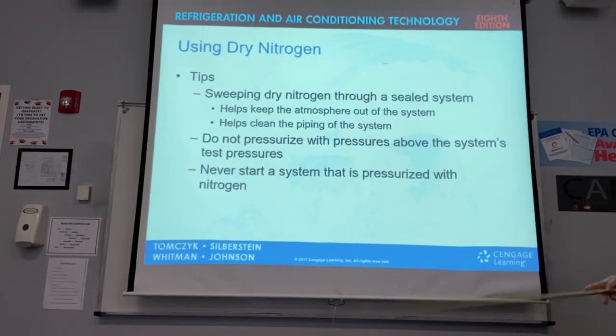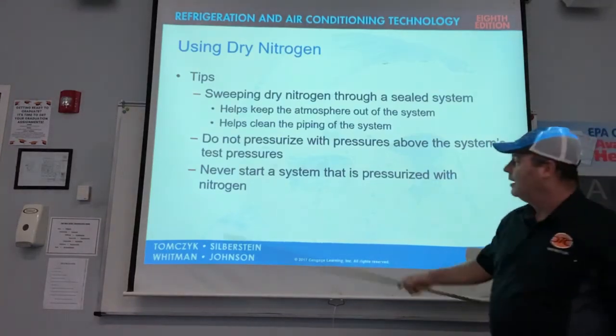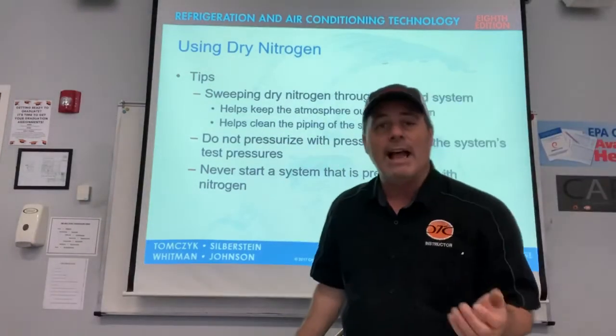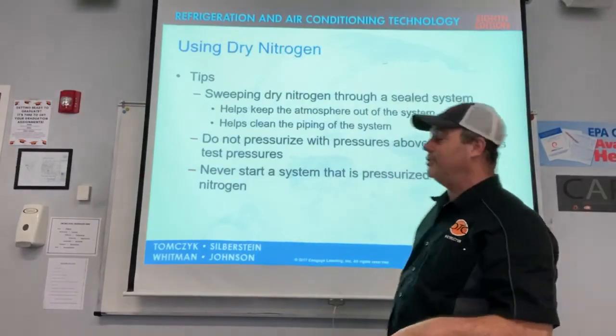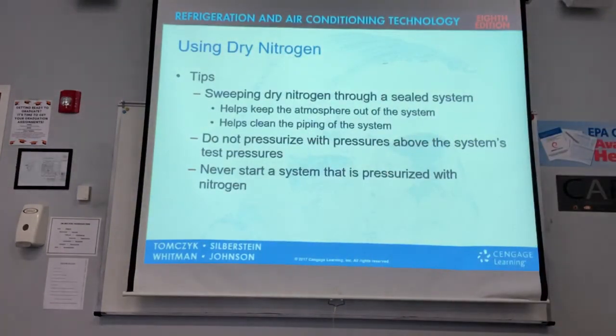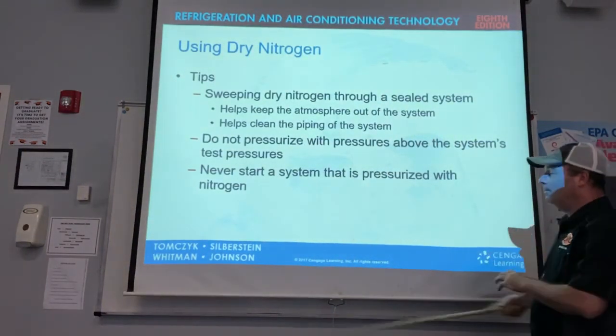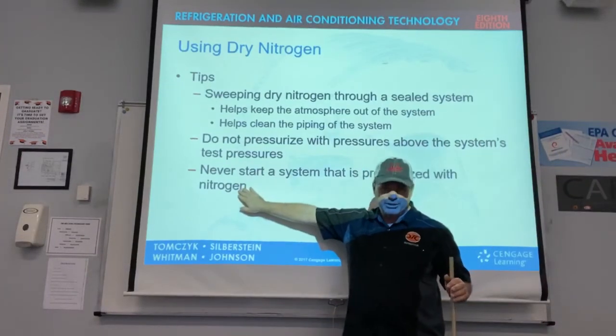Using dry nitrogen, if you read it here, they have some points. It doesn't matter if you release the nitrogen to the atmosphere. The EPA doesn't care, because the atmosphere is already 78% nitrogen. That's fine. Never start your system when it's pressurized with nitrogen.